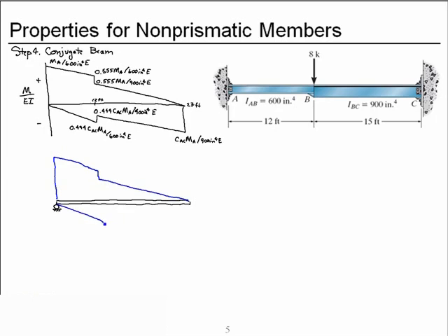And this distributed loading has an interesting shape, kind of a trapezoidal section and a triangular distributed load. Here a triangular distributed load and then a trapezoidal distributed load. So we're going to convert these distributed loads to equivalent forces acting at the appropriate place. And so I'm going to take this distributed load and divide it into regions.